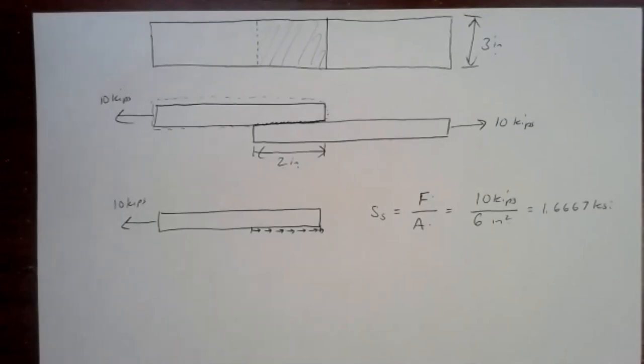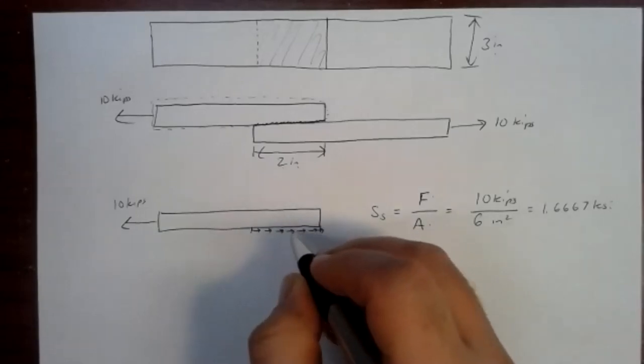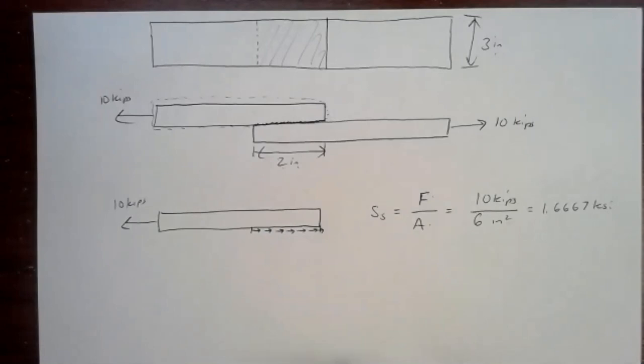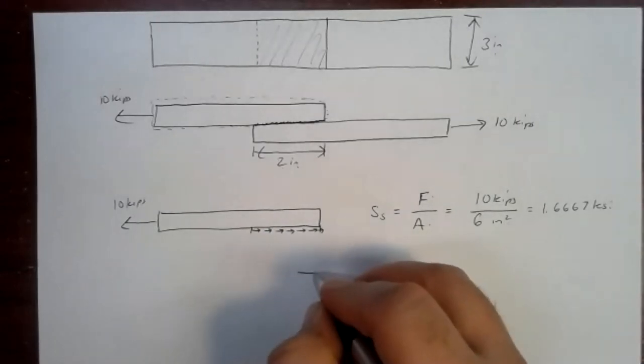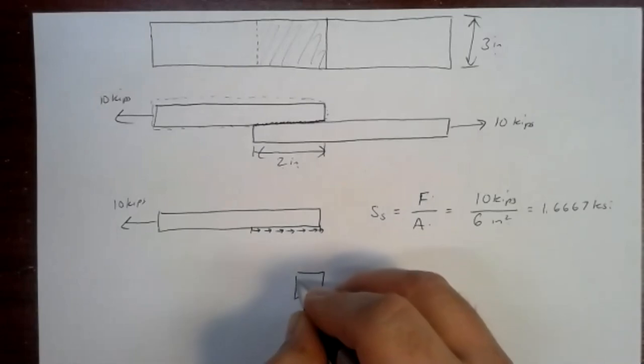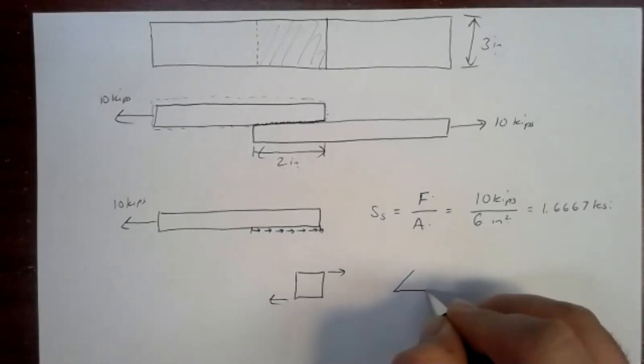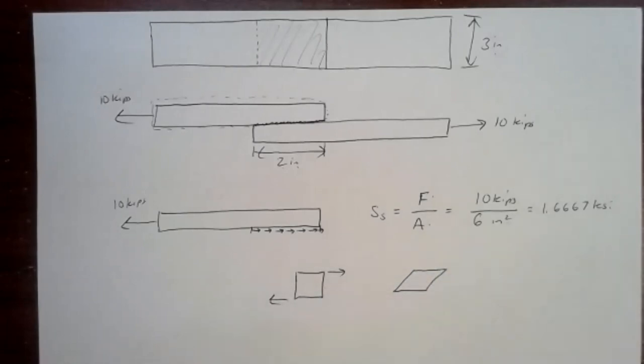In fact, this is actually a lot simpler. By one argument, it's a little more complex, but by the other, it's a little easier. We don't have the simple elongation idea that we had with normal stress. When you have shear stresses, things don't tend to stretch or shrink. What they tend to do is deform in terms of their angles. You start out with something that's rectangular, and if you put a shear stress on it, it tends to change the angle.